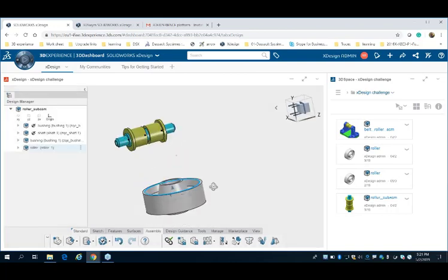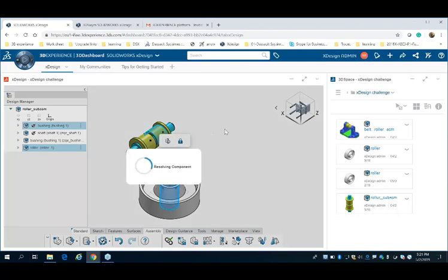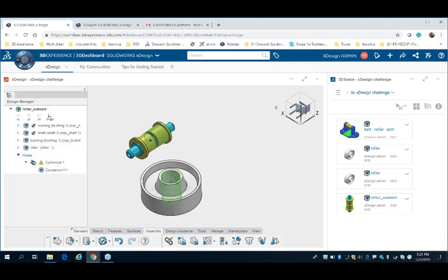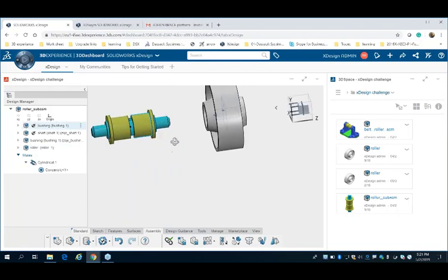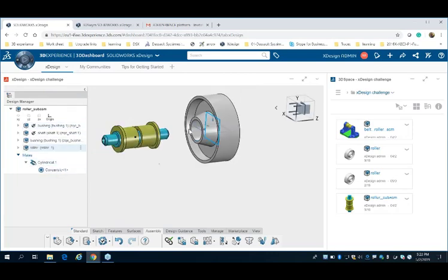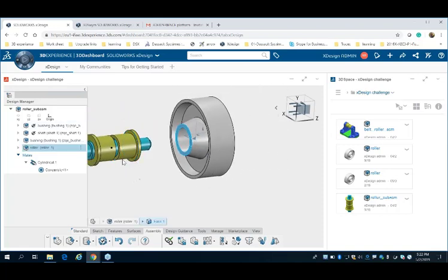The component is inserted. Now just select the sections. It will ask you to load the component. When you open an assembly, it is not completely loaded. So load all the components and it will give you a mate option. If it is completely loaded, then it does not show you any options like load the assemblies or resolve the assembly components. I have added a concentric mate. The mates will be added in the bottom section. Now select the faces.